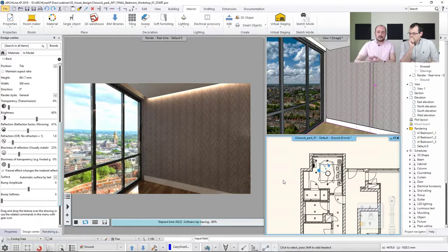And this is, by the way, a very good recommendation for how you should work with your project. When you have your design, and now we are focusing on the interior, you should have a layer set for one room. Like this room has lighting, accessories, and furniture, and those should be grouped to different layers. So you will be able to easily set up a very simple, a little bit more detailed, and a very detailed representation of the same room just by using the layers. So now I turn them on and I click on the 3D hammer.